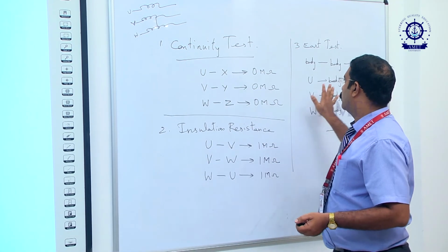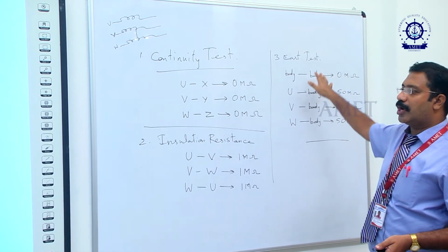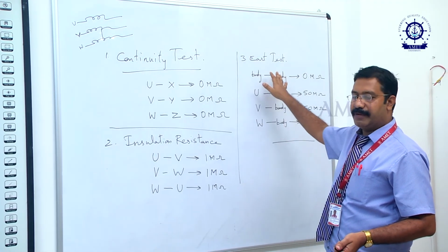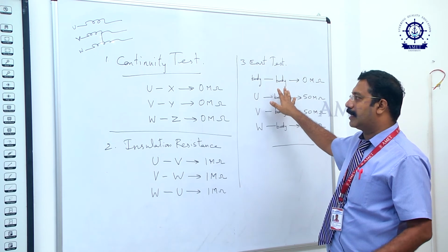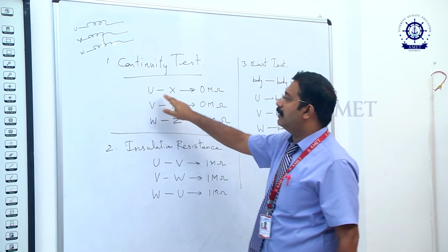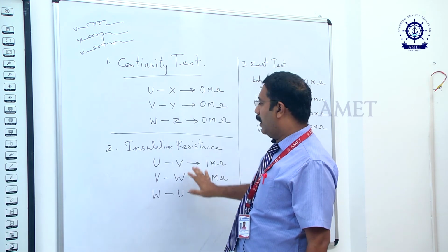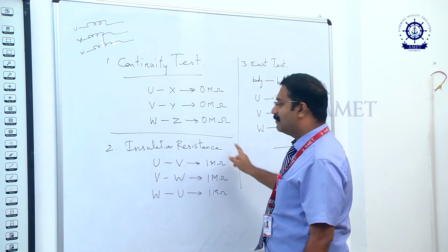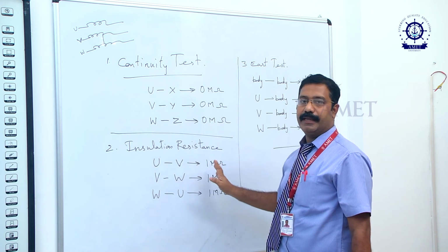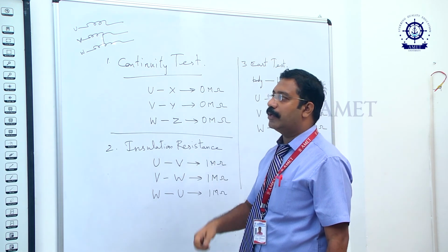Otherwise we can use the machine because there is no short circuit problem. Between the body as well as the conductors, and between each winding there is good conductivity. Only this value is less, but it's not bad. Therefore we can use the machine.